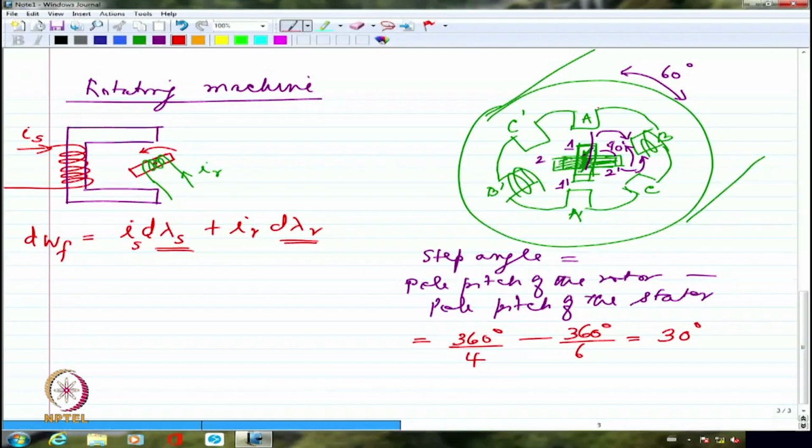If the 2 coils are mutually coupled, if one's flux is going to influence the other one, definitely they will influence each other in terms of the induced EMF. We can't help but have the influence, because you have a ferromagnetic core and the rotor winding is very much in the vicinity of the ferromagnetic core on which the stator is wound, and vice versa.